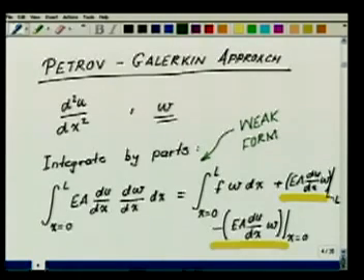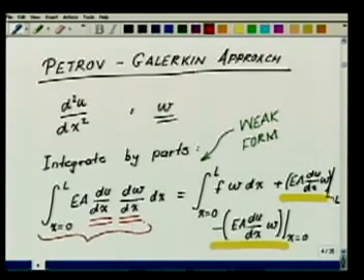Why was it called the weak form? Because you see that now we have weakened the derivative requirement for u. That is, only the first derivative of u is sitting in our integral on the left hand side, and we have passed that one extra derivative of u to w. So both u and w have their first derivatives sitting in the expression on the left hand side.